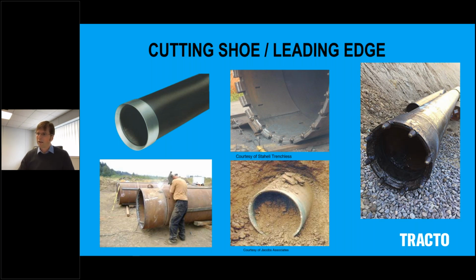If you are in difficult ground conditions, you can do things like here, top middle picture, where they are welding little carbide teeth in between the reinforcement sections. We've heard of people welding on bucket teeth, excavator bucket teeth. Your creativity knows no bounds here, and it is very much to the liking and in line with the experience of the contractor what is being done here.